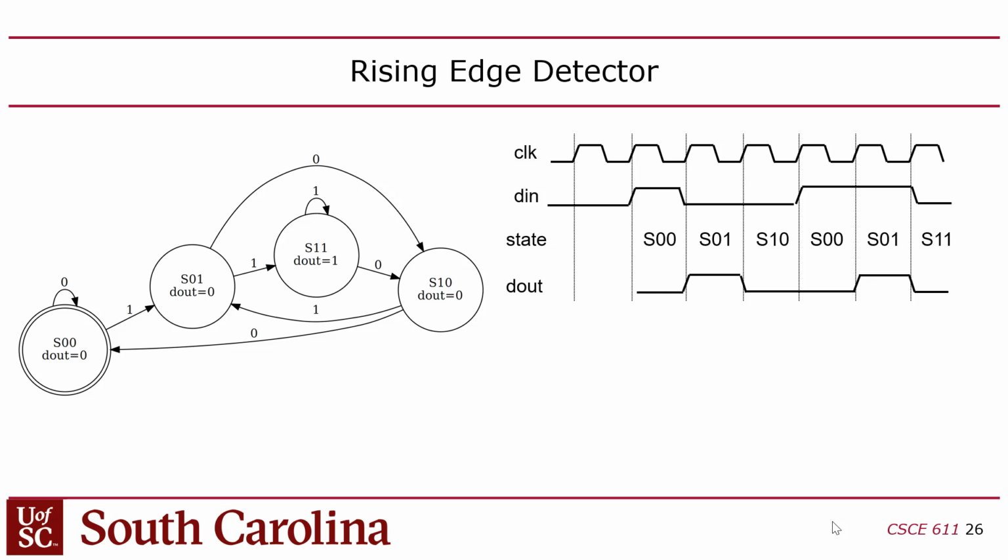So in this case, I get a rising edge here, but it's going to be a 1 cycle delay before I can have that pulse, because it's going to take 1 cycle for me to notice the pulse in a Moore machine, right? Make sense? So S01 should be a D out 1, right? Notice that the S01 has a 1, yeah, so I need to fix that.